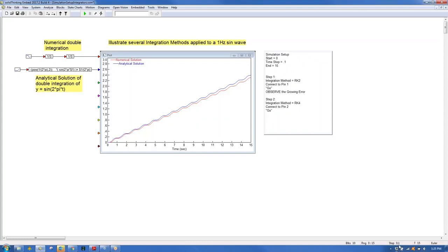Right now, as you see, I have it set to 0.1. I can decrease that, and that'll decrease this value. Or I can just move to a different integrator. But like I said, in an embedded system, you're mostly going to be dealing with Euler, and you will be dealing with pretty small update times. So this error will be acceptable pretty much in the design that you're using.